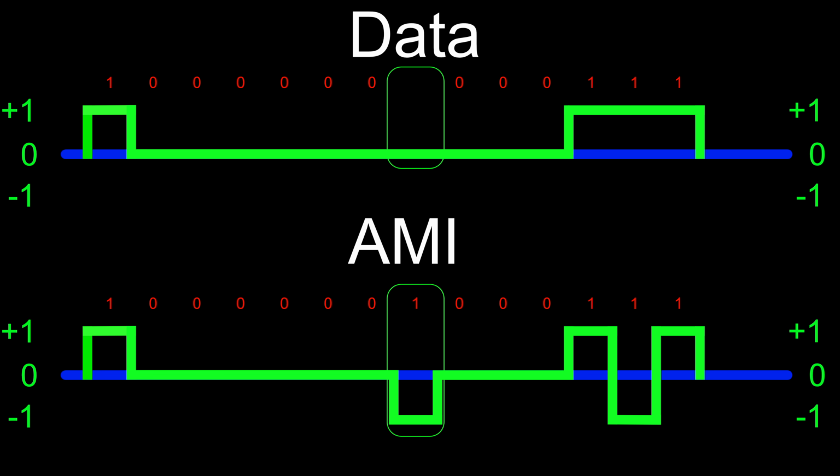To keep the timing in AMI, every 8th bit is just set to 1. This results in a capacity loss from the theoretical 64 bits a second to 56 bits a second, as 1/8 of the capacity is used for a fixed value, which is only to cover the case when more than 7 zeros are transmitted in a row.